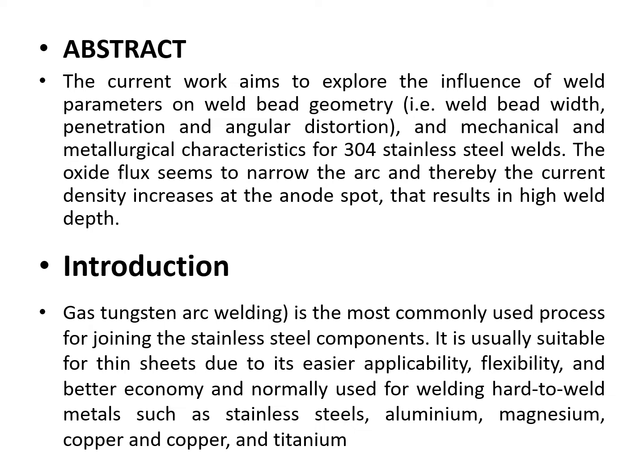Hence, in the current research work, 4 mm thick 304 stainless steel plates were welded by the ATIG method without groove preparation in a single pass, wherein the activated fluxes are self-developed and mainly consist of oxides that include TiO2 and Al2O3. The investigations aim to explore the ATIG welding of 304 stainless steel and to analyze the influence of oxide fluxes and weld factors on the weld bead geometry.